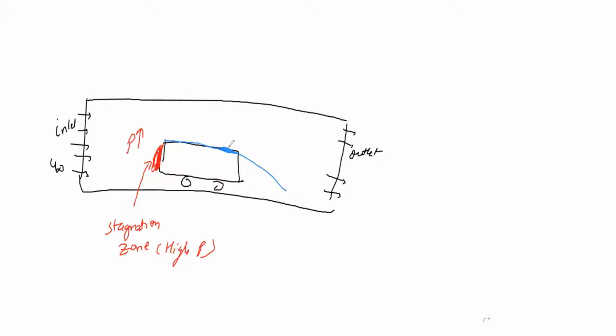Now since flow is separating from the wall, obviously there are layers of fluid coming, right? So basically this is U infinity, and here there will be a gradient. That we'll be discussing shortly. So this U infinity, or whatever velocity less than U infinity, to keep it general. Whatever the U which is less than U infinity in the boundary layer, with some velocity it is coming, right? But before this air came, whatever the molecules were here, they were not disturbed, correct?